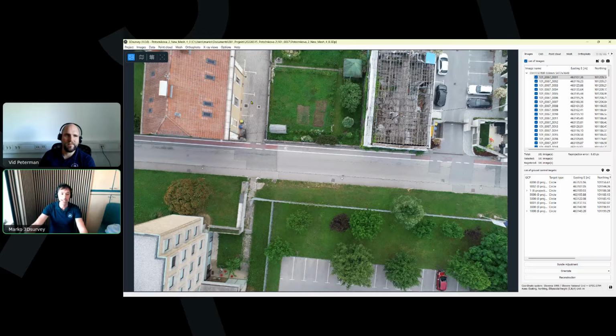If you would like to calculate a digital surface model for volume calculation, you are not going to go here and calculate a full 3D mesh, because the volume calculation is always performed on a regular grid mesh, so DSM, and you will go the old way here, okay? So two important things. With the reconstruction button, you get a new mesh. If you need to have digital surface models, so the regular grid mesh with a 1 meter grid cell size, you go here with the old workflow, okay?